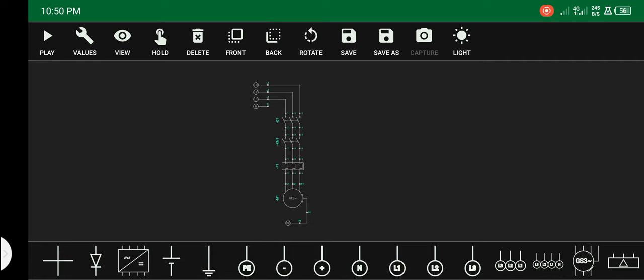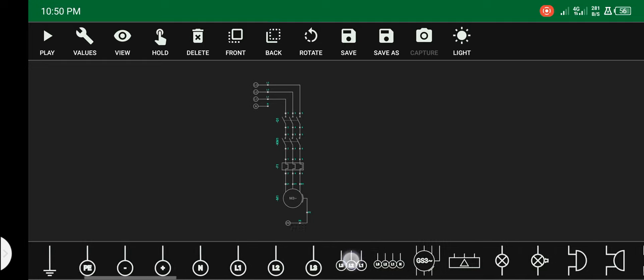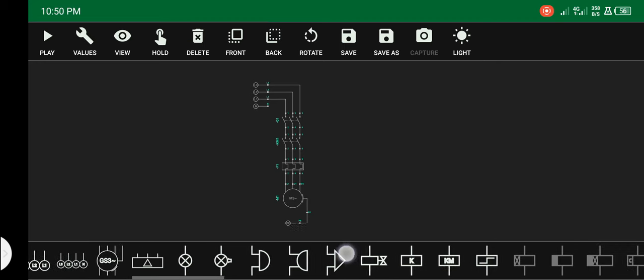circuit breaker, so we can just take from one terminal of the circuit breaker, the output of the circuit breaker, maybe on line 1 or line 3 or line 2. We can take one terminal. When you take a live and a neutral, L1 and neutral, it gives you 220. So the contactor, the coil which we're going to use at the end, is going to be a coil of 220 volt.